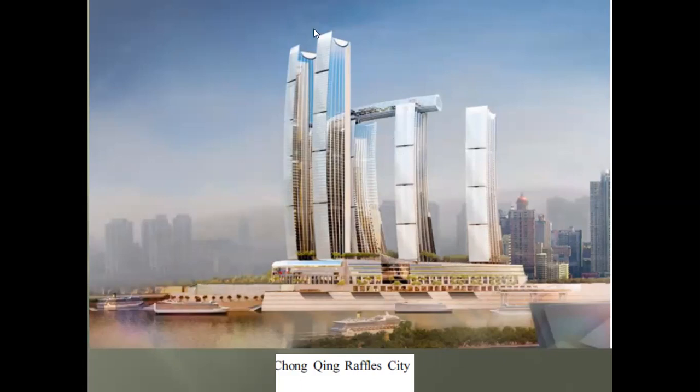So the greater the height of the building, like you see here, the more levels of the outrigger system. So the tallest buildings include 4 outrigger, maybe truss belt systems. Some buildings with less height in comparison with this one include 3 main outrigger systems.